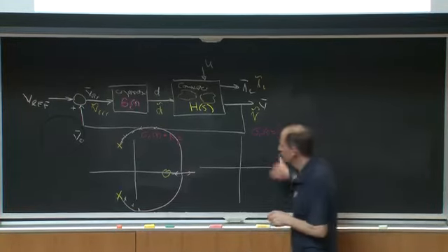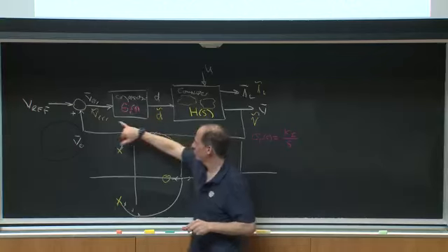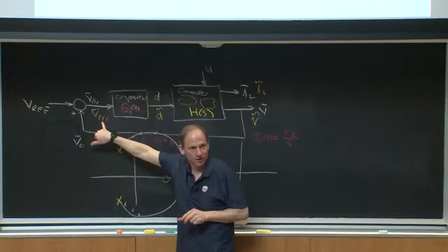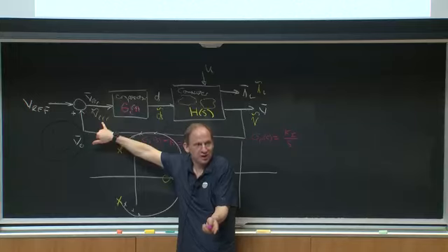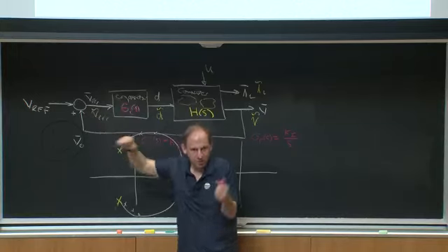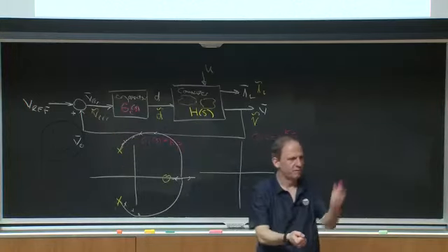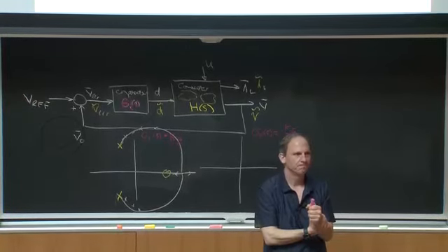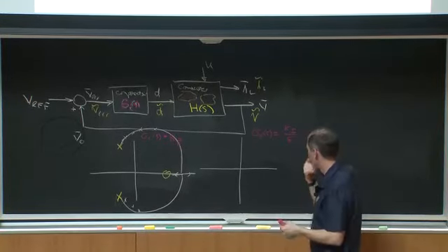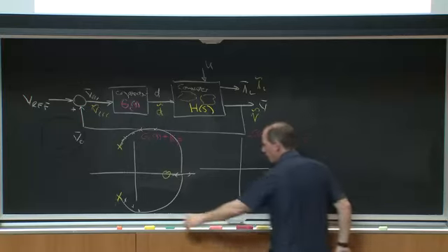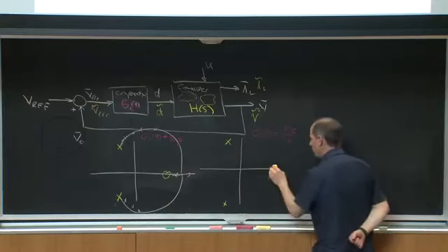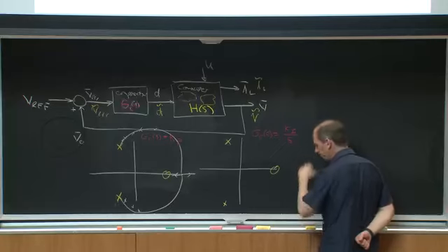So what I could do is instead of making my D proportional to the error voltage, I could make it proportional to the integral of the error voltage, right? So P and I are parts of PID controllers, right? And the beauty of an integral controller is eventually it will integrate up the error and leave me with 0 steady state error. Okay? So if I did that, I still have my plant poles. I have 2 lightly damped plant poles and a right half plane 0.